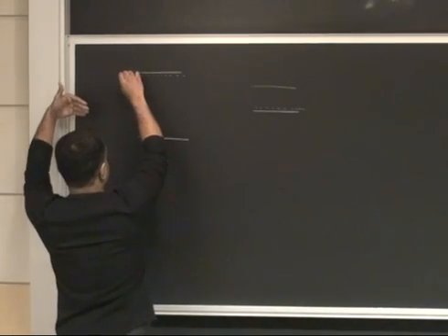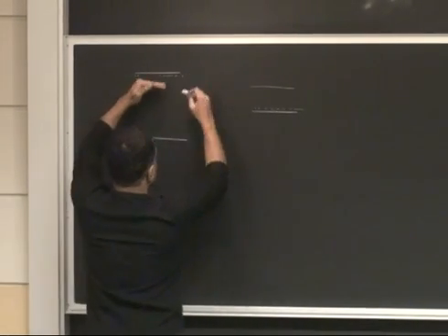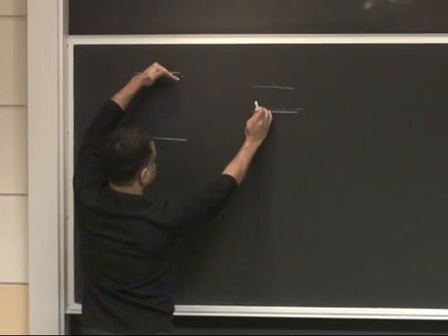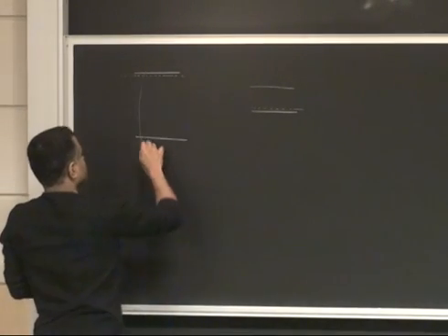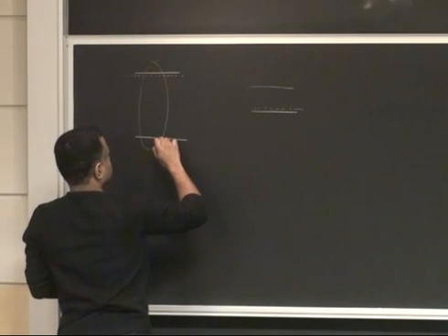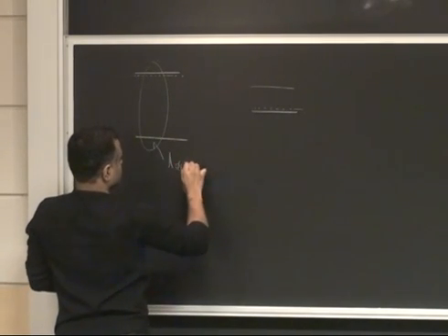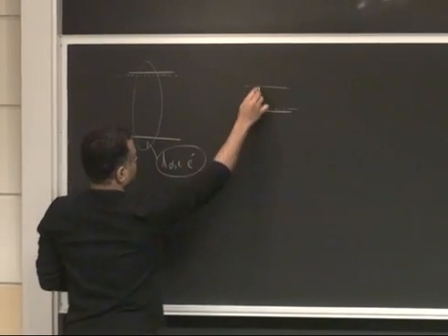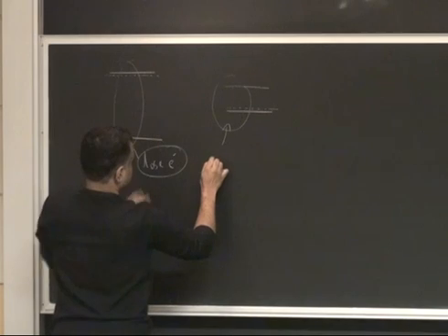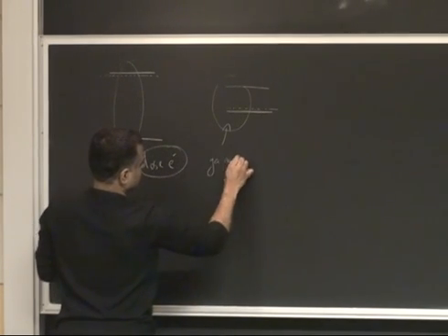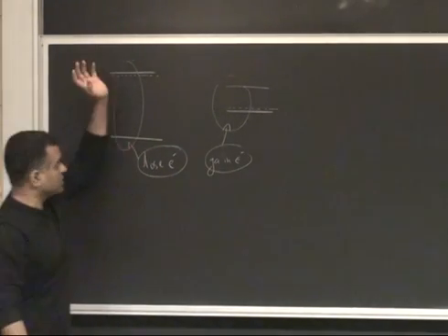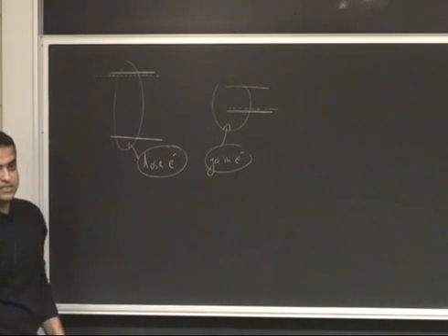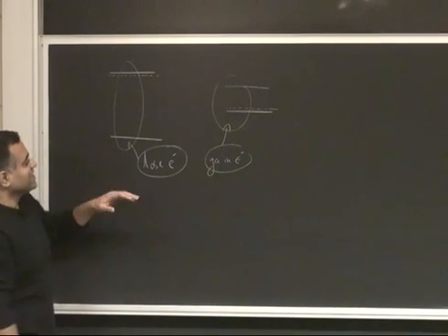The other thing you realize is that because the Fermi level is higher here than in this region, this layer is going to lose electrons, and this layer is going to gain the same electrons that are lost by that layer. Is that clear? Wherever the Fermi level is higher is going to dump electrons in the other layer.